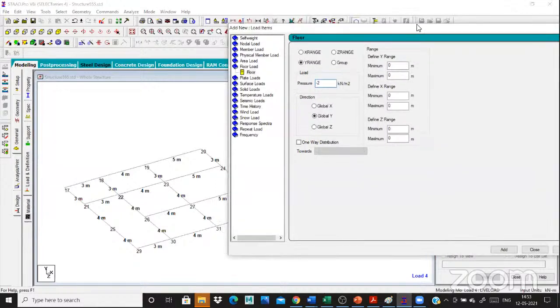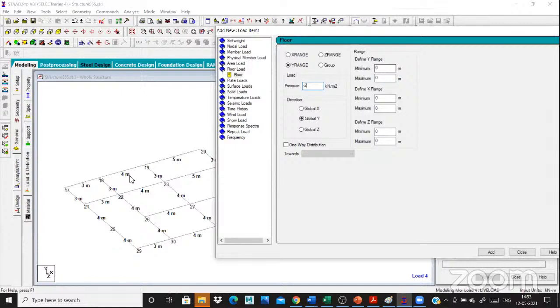Simply go to -2. Same procedure, starting from bottom. This is 0.02, total 18 meter. Okay, X is a square slab. X is 3. Sorry, X is 0. This point, this is 3 meter. Simply click this 3. Then go to result also 3. Then add, close. This live load will be taken to all the floors.